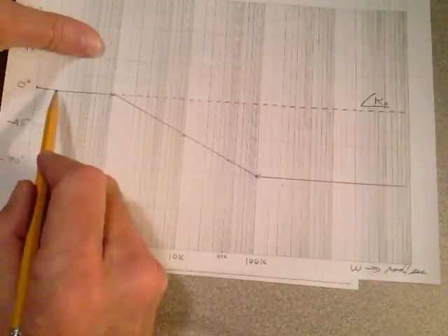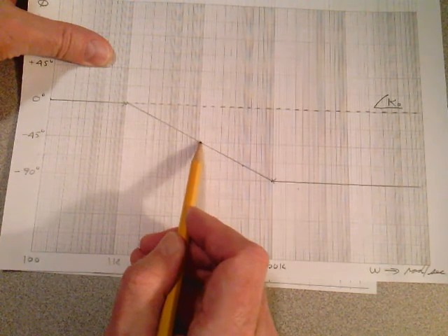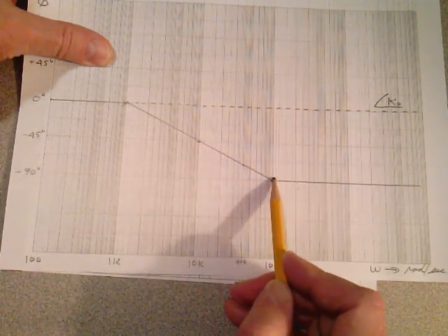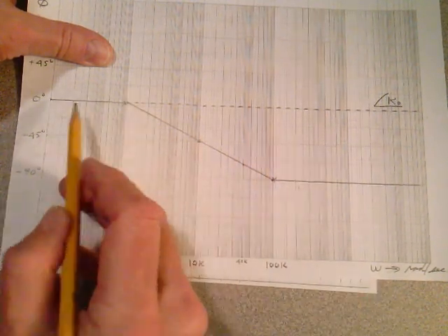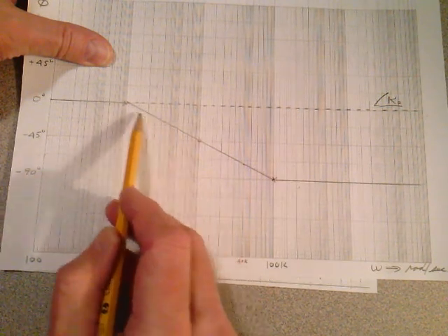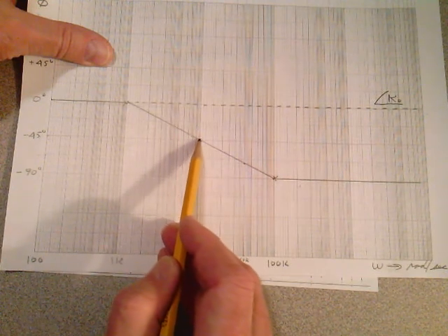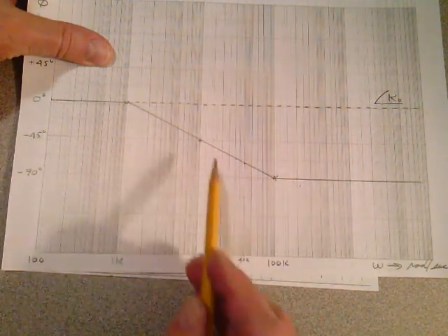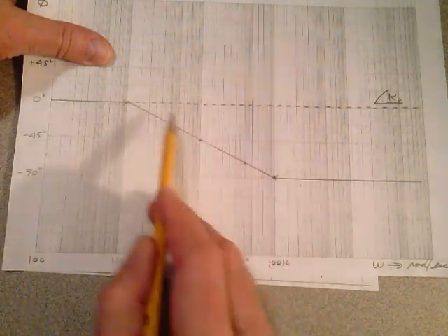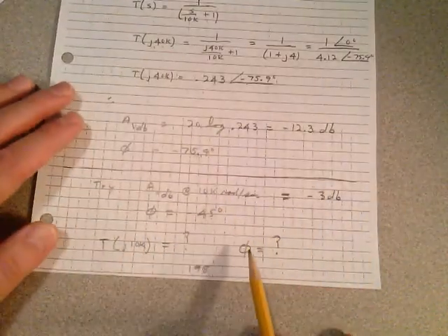The actual phase curve is asymptotic at this point. It comes down, it crosses over here, and then it's a little high on this point down here, because it's asymptotic to this line, and asymptotic to this line. So you have to picture that actual curve of phase coming in, going above here, rolling off, coming below here, rolling off, crossing right at minus 45 degrees at the break frequency, and then coming above and being a little high down here. But these aren't 3 dB points at this point and this point, because that's angle we're talking about. So you can do very good approximations.